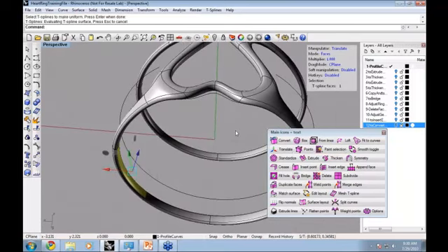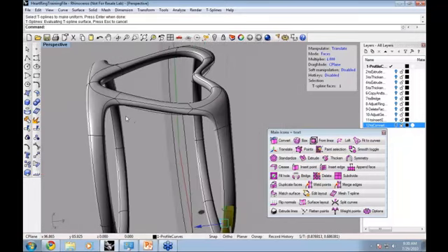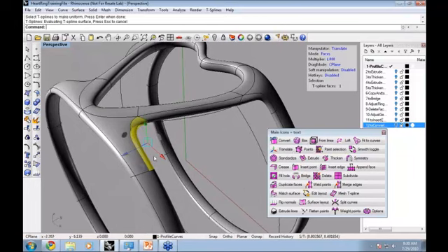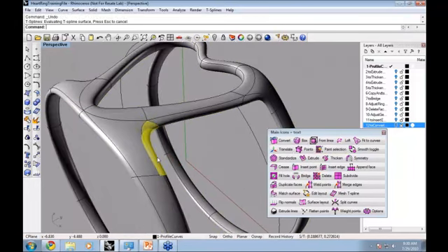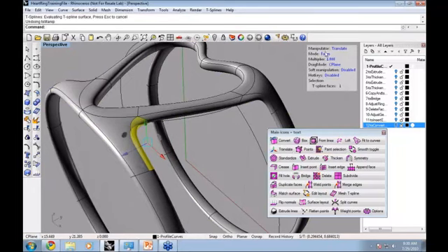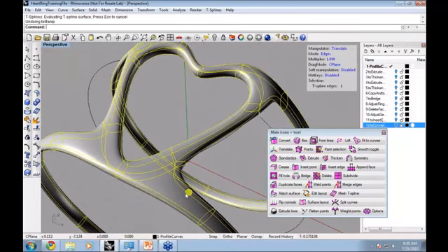And what that does is just relax everything after the bridge. So all of a sudden we've got a very nice smooth surface, and look at these transitions. Remember, this is still a T-spline, so you can still move these around, and you can move the edges. You can click here to move faces or edges, and the surface just updates beautifully. It just stays nice and smooth there.